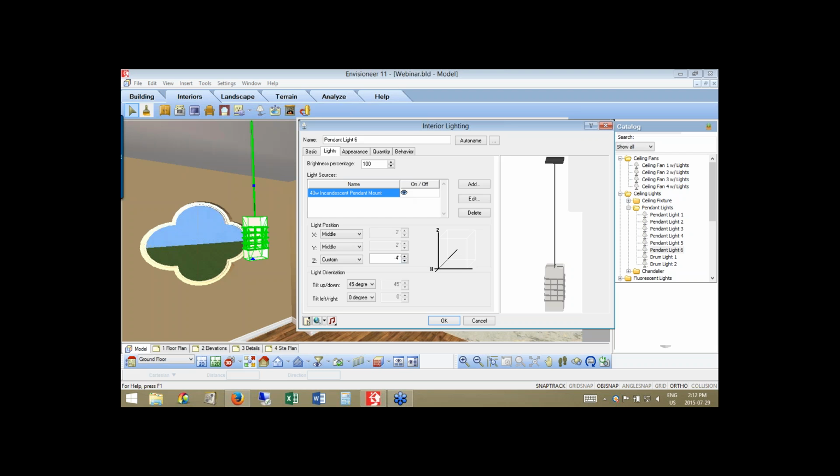You can strategically put it a little bit lower. I often put them a little bit lower for a hanging light on a ceiling, so it's not too close to the ceiling and it's not going to create that burn mark on the ceiling. Lower that value down a little bit. And if you want to direct the light in any way, you can use these light orientation options here to tilt the light in a different direction. So that'll affect the lighting.